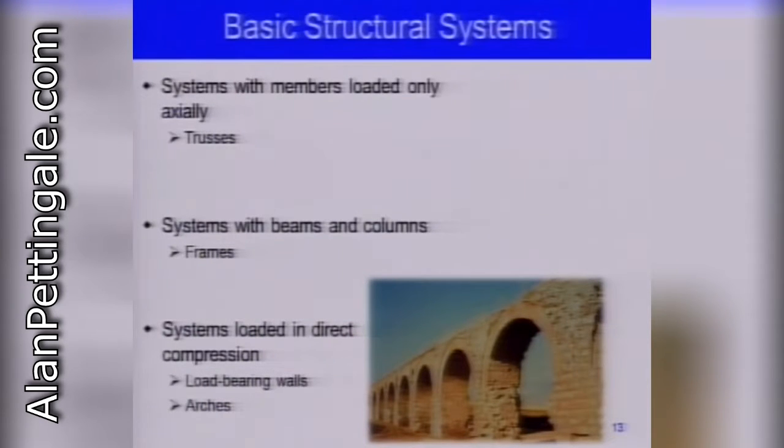You can see the arches are a very smart structural system, and it's very pleasing to see. It looks really nice, and it only takes compressive forces. So we have the loads applied on the top, and then these are transferred around the arch to the pillar.